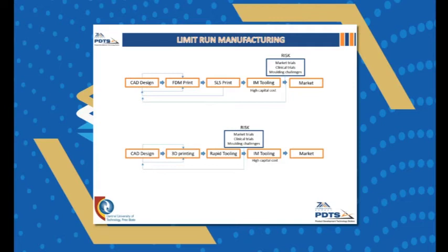So we have researched this, as I have mentioned, and we came up with the next development process. You start off with CAD design and you 3D print just like in the top process. But we utilize rapid tooling before we move to injection mold tooling. Now, what is rapid tooling? Rapid tooling is the creation of an injection mold tool with additive manufacturing. As I mentioned, additive manufacturing has a few processes which you can utilize, as well as different materials.